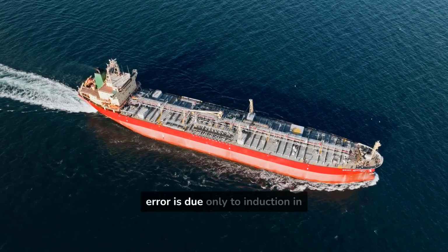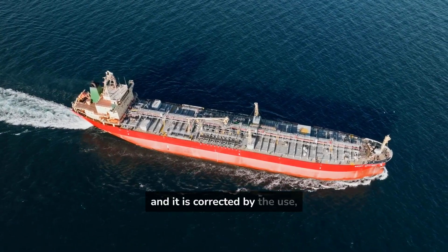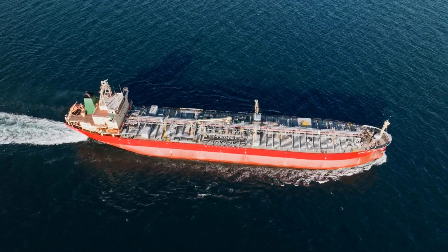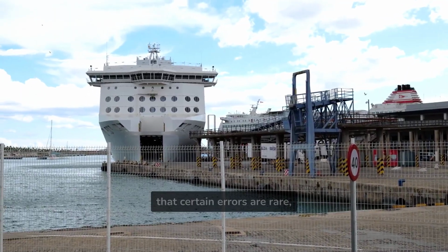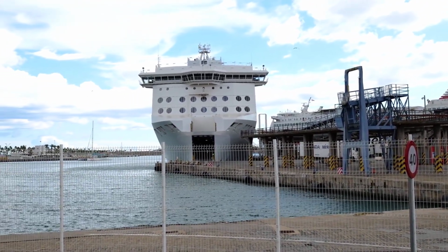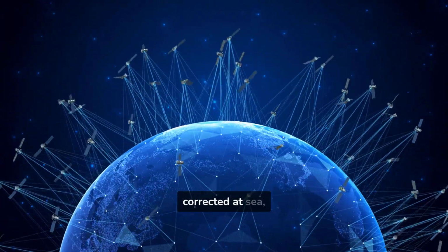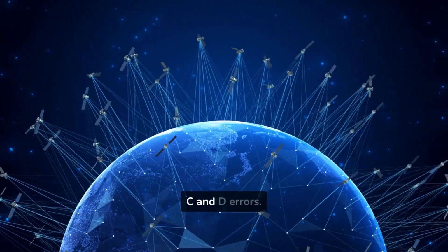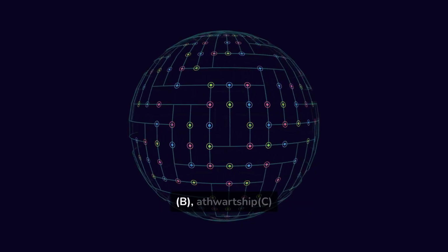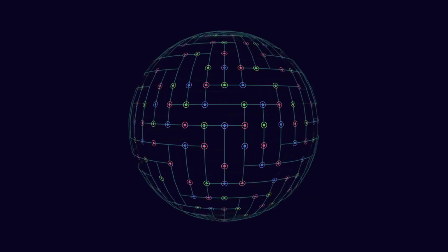The D error is due only to induction in the symmetrical or horizontal soft iron, and it is corrected by the use, only, of the spheres athwartship of the compass. To sum up, the discussion above reveals that certain errors are rare, others have been corrected at dockside. Therefore, for most ships, there remain only three errors to be corrected at sea: the B, C, and D errors. These are corrected using fore and aft, B, athwartship, C, magnets, and quadrantal spheres for the D error.